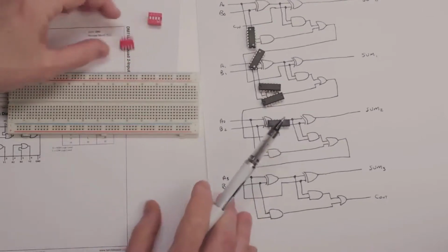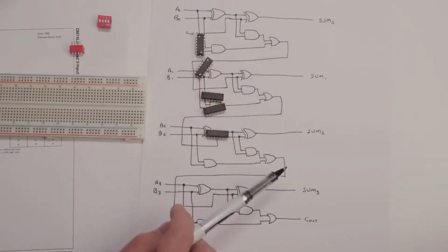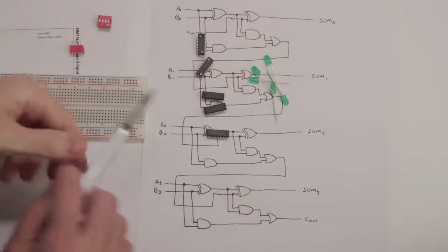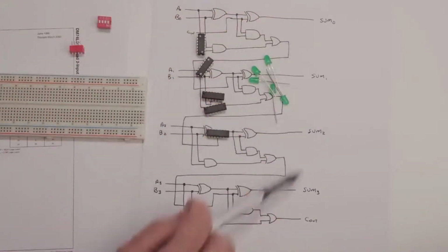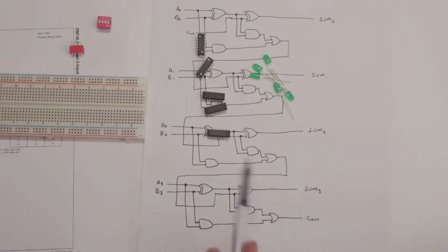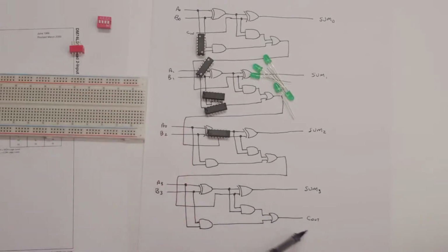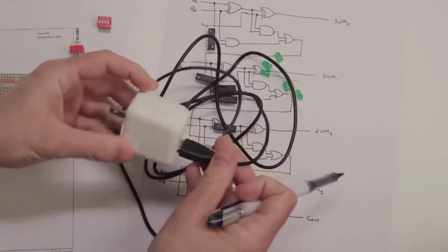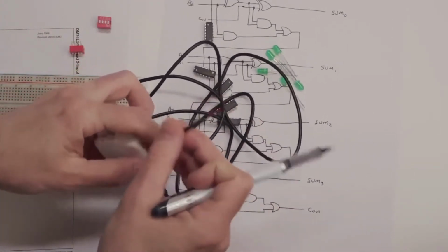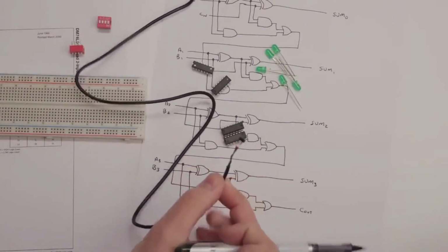And then finally, a couple other things we need are some kind of outputs here. So we have our sums coming out here. I just have some little LEDs that'll light up for each of these digits. I have 5 of them because there's 4 outputs plus the final carry, because if you're adding two 4-bit numbers, you might end up with a 5-bit output. So that last carry will have another LED for that. And then I'm just going to power it with a little USB. This is just a standard USB charger that I've hacked the end off of and just taken the red and black wires out of there, and that'll give us 5 volts.